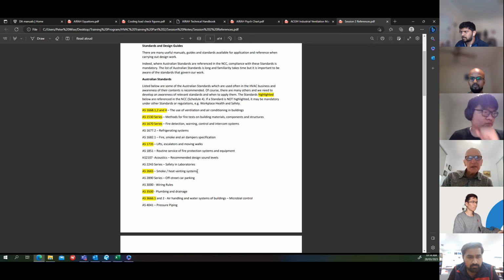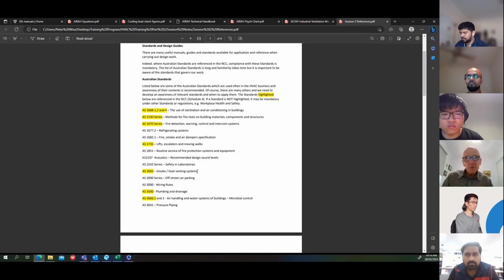What they are is like a fire damper sitting on the roof of the building. You'll have several of them, in an array, and when there's a fire, they open up and let the smoke vent straight out. So if you've got a single level warehouse with a roof over it, which might be, say, 8 metres above the floor, these systems are quite good. They work automatically. There's no real control system involved. They just open automatically and let the smoke out.